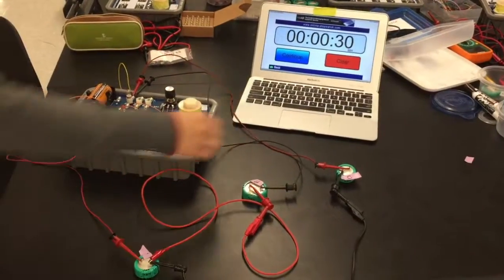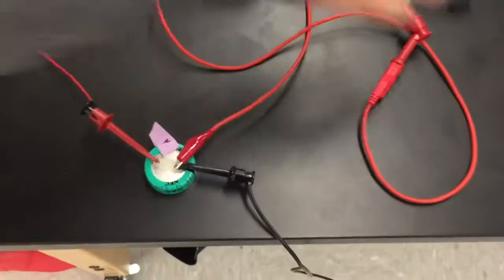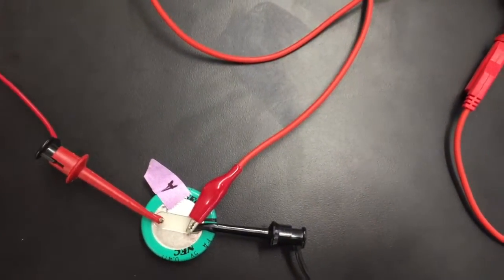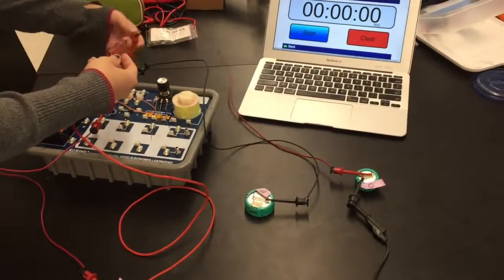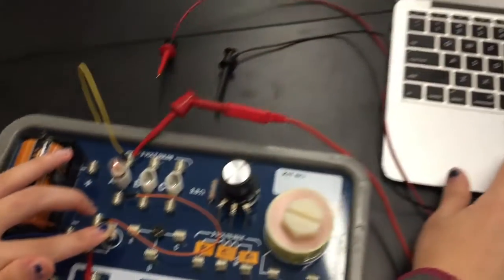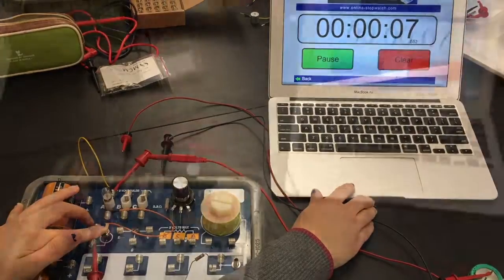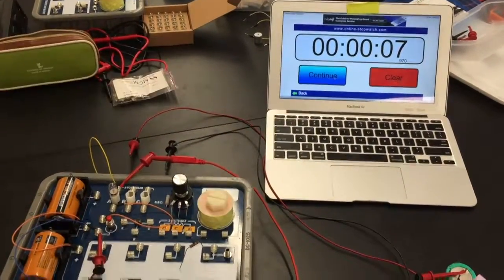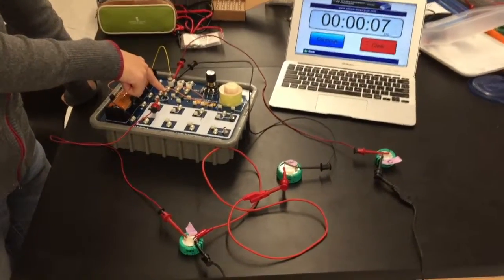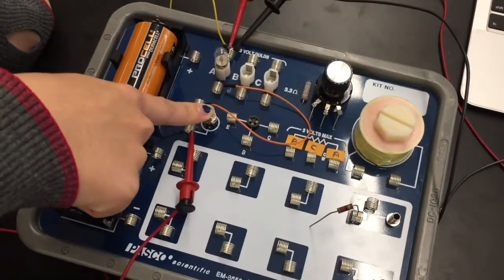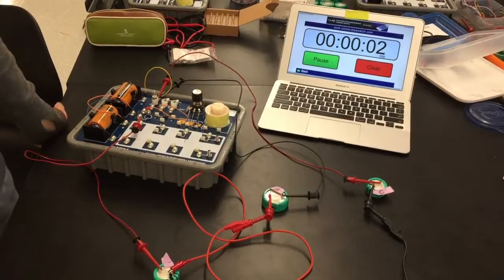So now all of the capacitors are charged, and we're going to see how long it takes capacitor A specifically to get discharged by hooking it up to the light bulb and by disconnecting the other two capacitors from the circuit. It took about 7 seconds for capacitor A to discharge. So now we're going to discharge all of the capacitors by turning on the light bulb. And we're going to charge them again for 30 seconds for our next experiment.